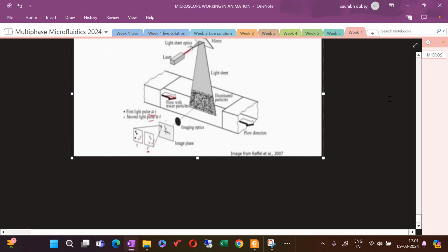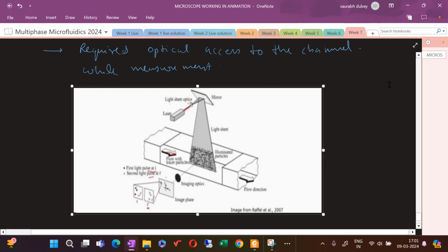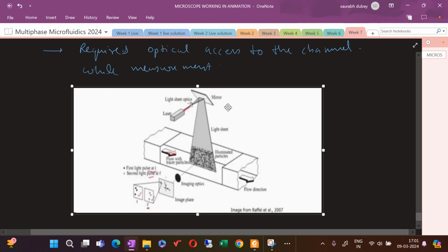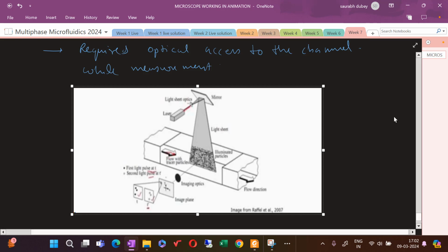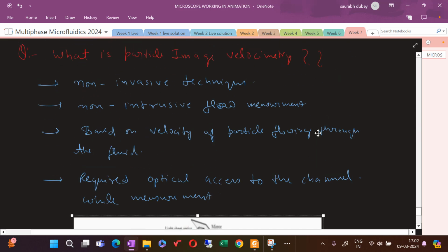So you need the tracer particle, a laser and optics, a camera, and a synchronizer, which will synchronize the phenomena happening with the light, the fluorescent effect of the particles, and also the FPS, frames per second. And there are different post-processing devices that will help you post process the data. There are some properties of the tracer that have to be considered.